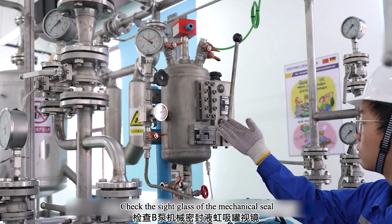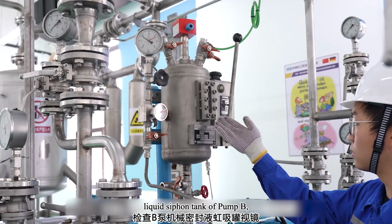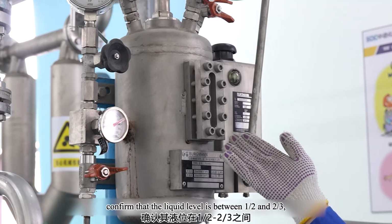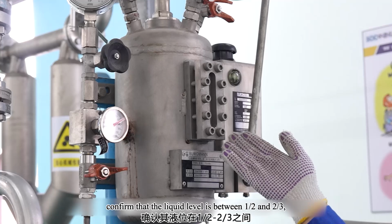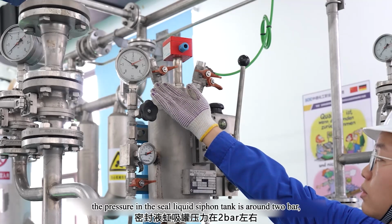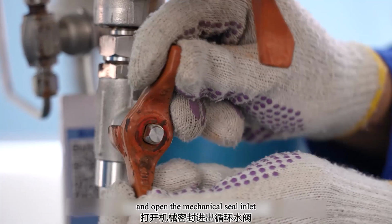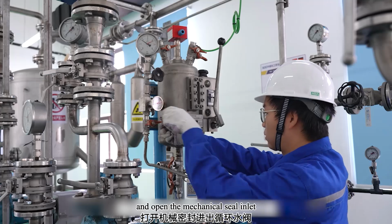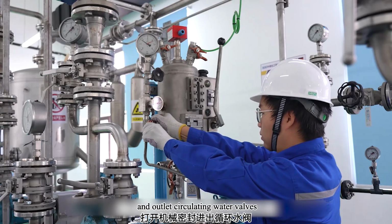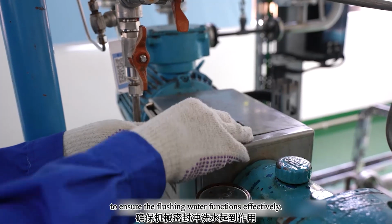Check the side glass of the mechanical seal liquid siphon tank of pump B. Confirm that the liquid level is between 1/2 and 2/3. The pressure in the sealed liquid siphon tank is around 2 bar, and open the mechanical seal inlet and outlet circulating water valves to ensure the flushing water functions effectively.